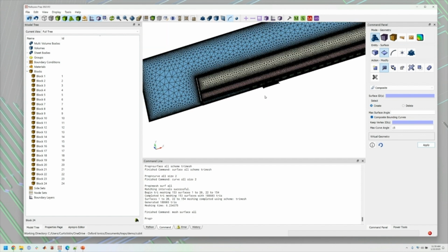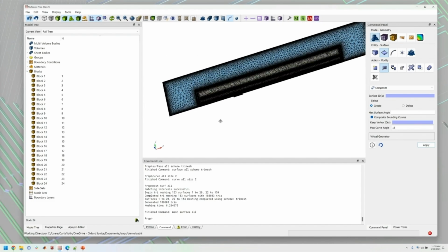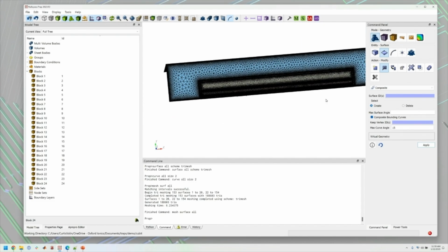In a lot of the really, really big models, we might be memory limited. And so having a model that is half as big gives you substantially less memory requirements. Again, something more than linear. So you can run a much bigger model using the symmetry. If your model has symmetry in the x plane as well, if the plus x is the mirror of the minus x, then you can run just a quadrant of the model and run 4 simulations. Again, if you have the licenses to do that, that can take you essentially 1/16 of the amount of time to run.